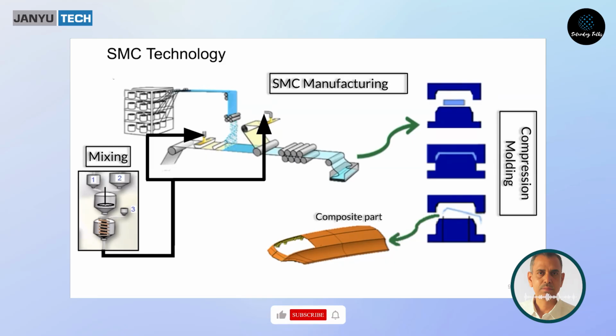Then after manufacturing, we keep it in controlled condition at 30 degrees centigrade temperature for minimum 24 hours up to 72 hours, depending on the maturation level we expect, which we measure by the viscosity increase. That is basically how the material is thickening with the help of the chemical thickener. That viscosity is minimum 10 million cPs and above.